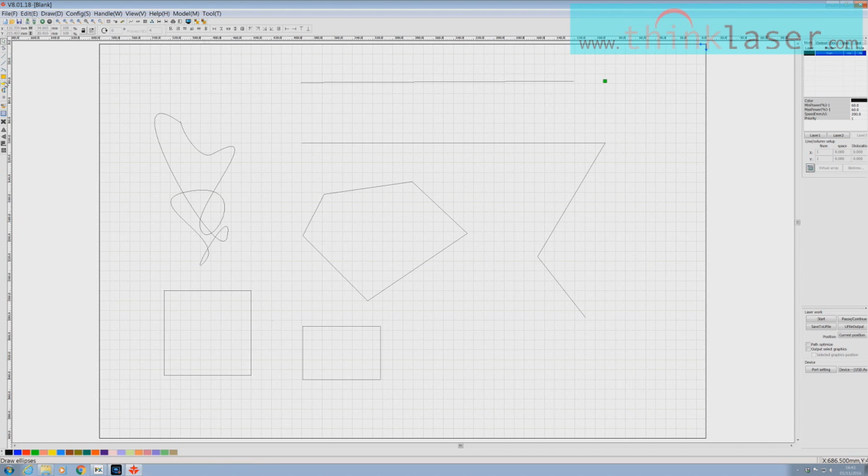And the same logic applies to the circle. Well, it's not a circle, it's an ellipse tool. Again, I can't click and click. I've got to hold it down, drag out an ellipse, and either let go, in which case I shall get the ellipse, or I can hold down the control key and move the mouse and I get a circle. But I've got to let go of the mouse before I let go of the control key.